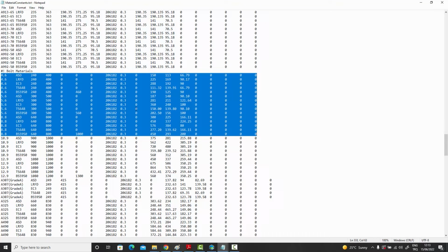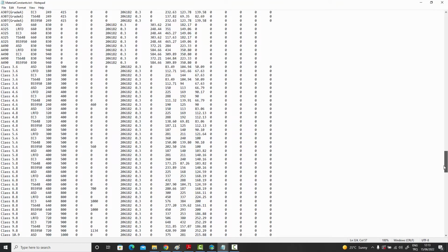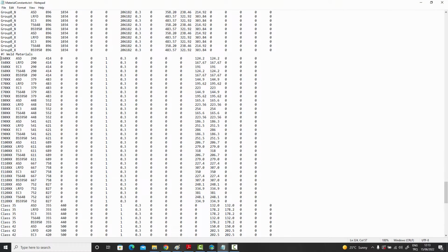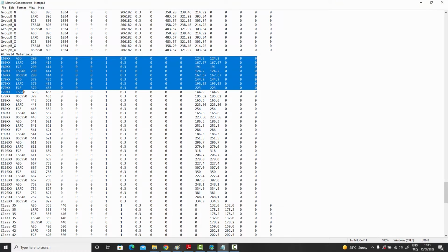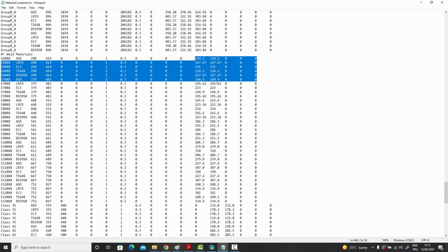So for some of them, for example, these last numbers are always 0 because these are weld-related strengths. And if you go down further, maybe we can find some, yeah, okay, over here we have the electrodes, E60, E70 electrodes, and in these electrodes we have these allowables filled up for us.